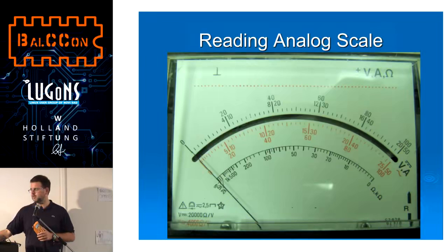And you look at what value you're going to read out. So if you are going to measure 500 volts, 50 is the number of these marks that's very useful. When the needle shows 50 marks, that means 500 volts if you are measuring at the 500 volts range. So you just scale that number of marks to that voltage or any value that you're measuring.